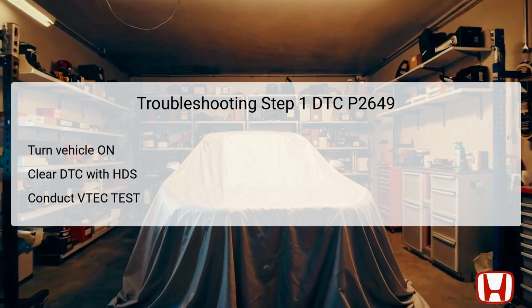After clearing the DTC, conduct a VTEC test via the HDS inspection menu. This test assesses the functionality of the VTEC system, helping to determine if the solenoid and related components are operating correctly. Following these steps will provide initial insights into the malfunctioning system.